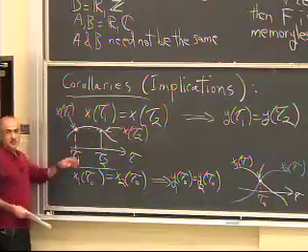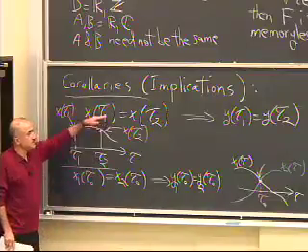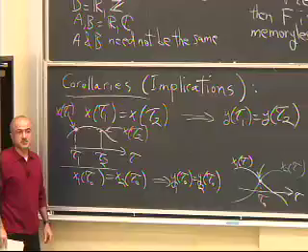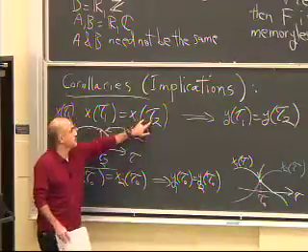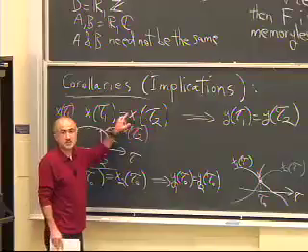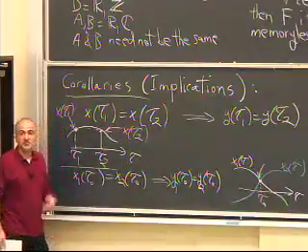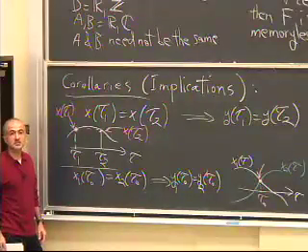So you can play around with all such permutations of these scenarios and use these corollaries if you ever want to disprove that a system is memoryless. Find two instants in time, for example, where the input signal has the same values and see if the corresponding output values are the same. If they're not, then you can write it off as a system that has memory.